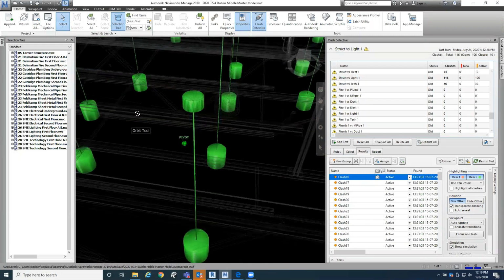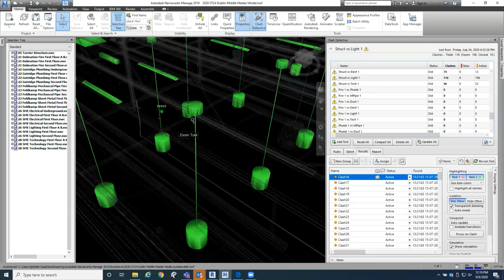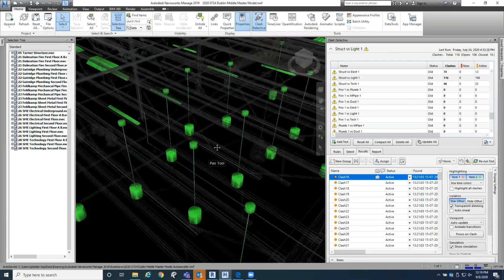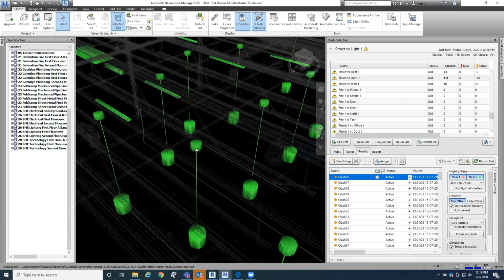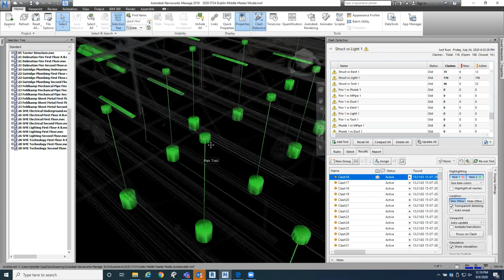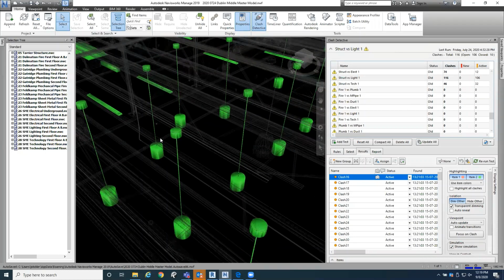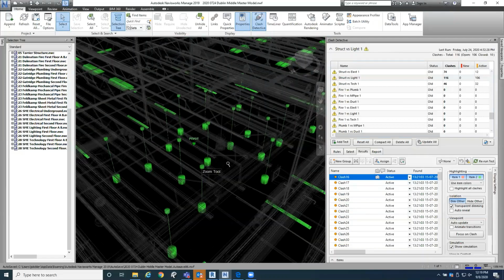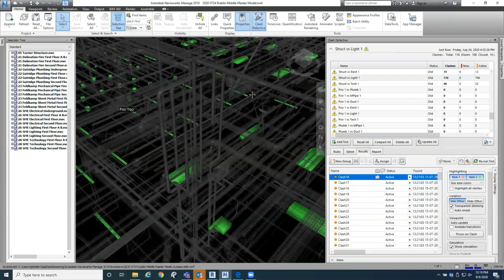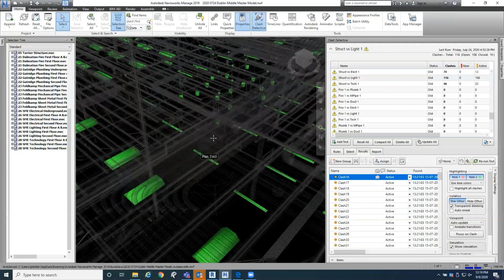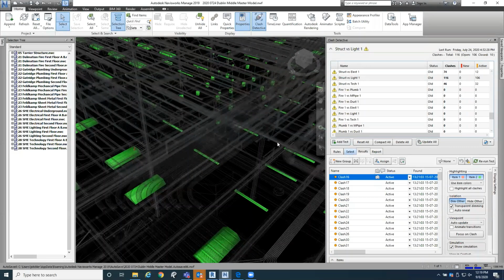They've got their mounting cord into the steel, so they read as clashes even though they connect into the steel. It's where they're supposed to be. So you'll still have clashes showing; you just have to discern what is relevant and what you're looking at.